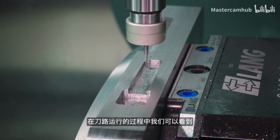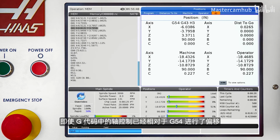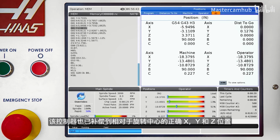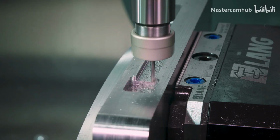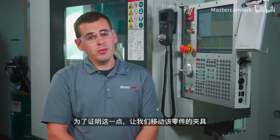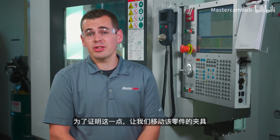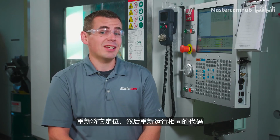As this toolpath runs, we can see that even though the axis commands in the G-code are output with respect to the G54 fixture offset, the control is compensating to the proper X, Y, and Z positions relative to the center of rotation. To prove this point further, let's move the fixture for the part, pick up the new fixture location, then rerun the exact same code.